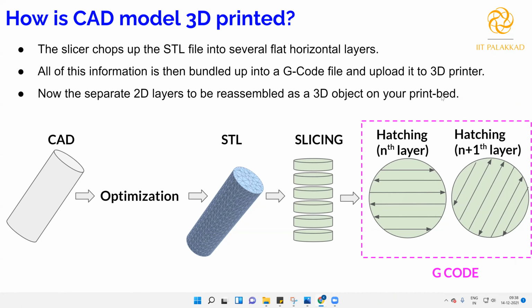Once the slicing is done, you are making this component into very finite objects. You see, now I can make these small slices in 2D, right? You see here STL, then I'm slicing, then I'm taking any one slice. Now actually I simplified the problem into CNC. Now I can use CNC code, G codes, right? I can apply the G code. I can make the tool move in X and Y now, right?